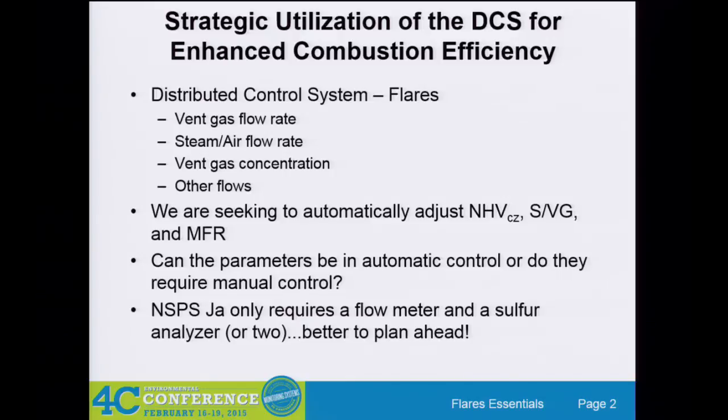Some people have thought about doing it external to the DCS in some sort of a data acquisition system, and then feeding the important parts back to the DCS just to minimize that, because especially at some of the older facilities, the DCS is already maxed out and they can't handle it. They'll bog it down. So they're saying we want a way to have it external and then only feed those parameters that an operator would actually have to know when something's going wrong.